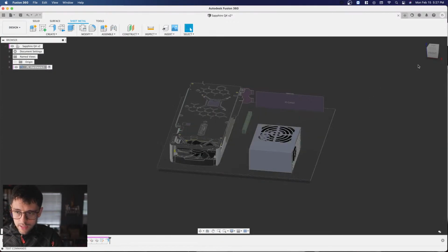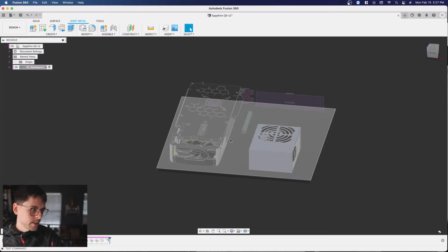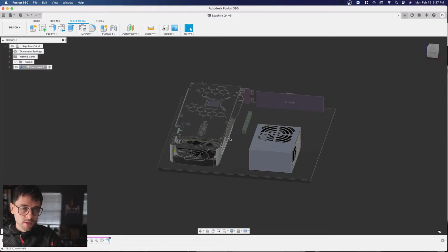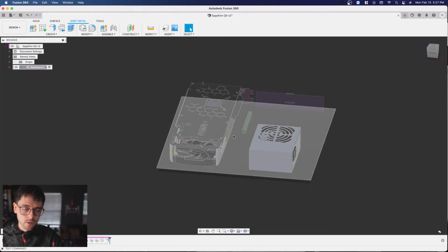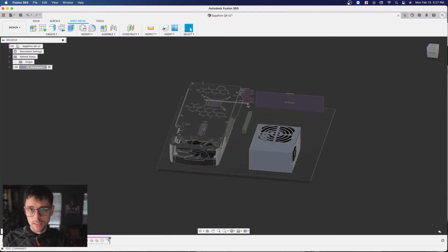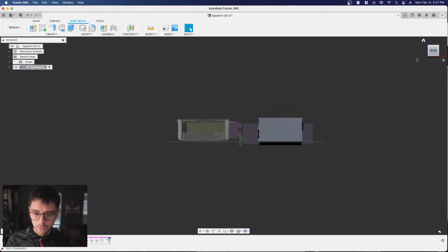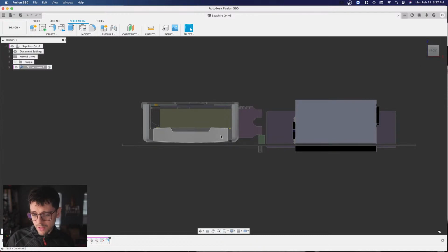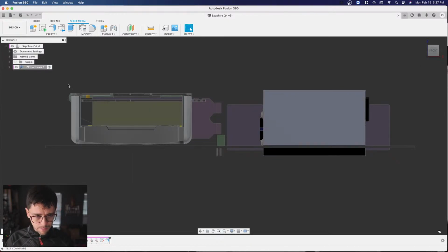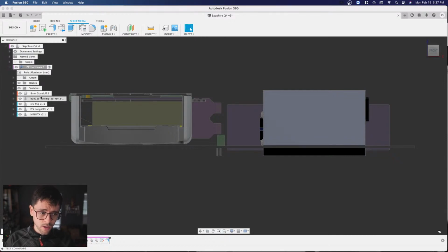Okay, so I have a 2 millimeter thick panel. 2 millimeters is the thickness of the S4, the Skyreach 4 Mini cover panels and the front bezel. The rest of the Skyreach 4 Mini is 1.6 millimeters thick aluminum. So for those tight, thin bends, it's 1.6. These are going to be a really simple bend, but again, I'd prefer 1.6. I'm just going to start off with 2.0, and I can change things as I go along.